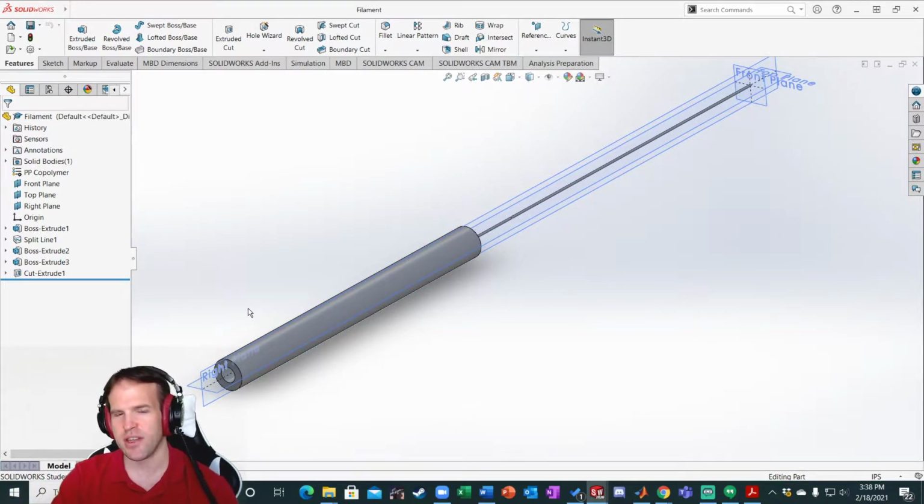Just as a simple approximation to get started. Realistically, towards the hopper, you're going to have plastic pellets coming in that will have air in between them. And they're going to be individual pellets that are going to move through the screw system and start to melt. And then eventually, towards the nozzle, we'll have fully melted plastic, and so it will look something like this with the parameters of plastic.